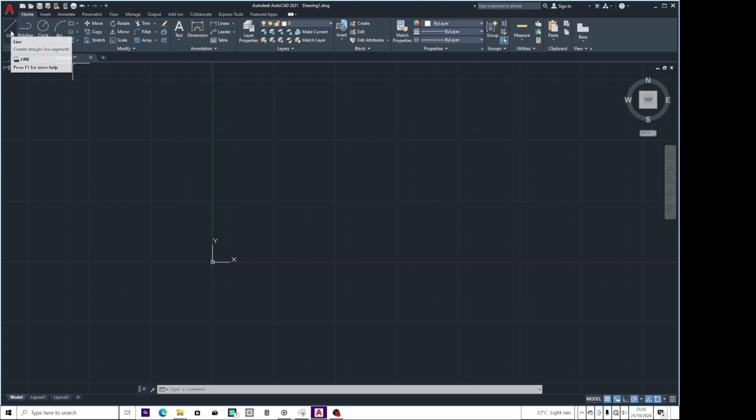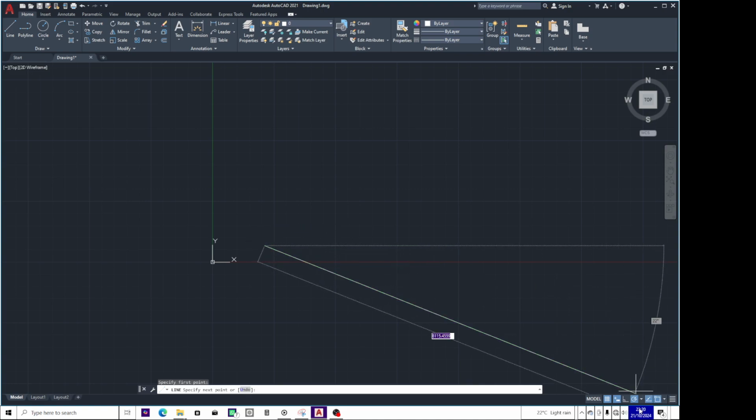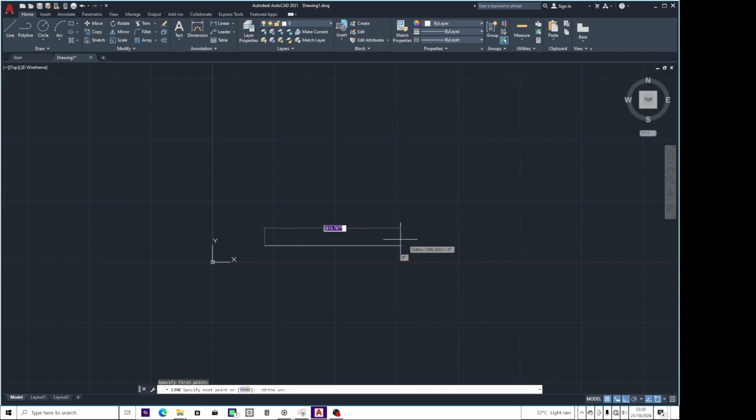Fine, let's see how it operates. Once I have a line, I can activate now my ortho mode. Now, if I need to draw a line at the end or the center, you see that we can find the midpoint, we can find the center, we can find etc., name them. That tool that helps you find the end point, the midpoint, and any nodes is this tool.